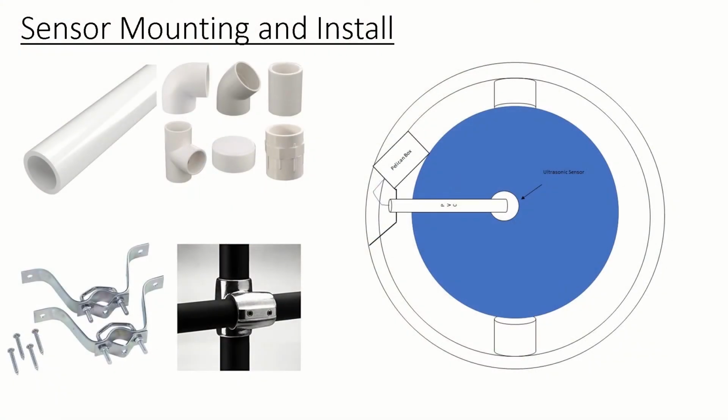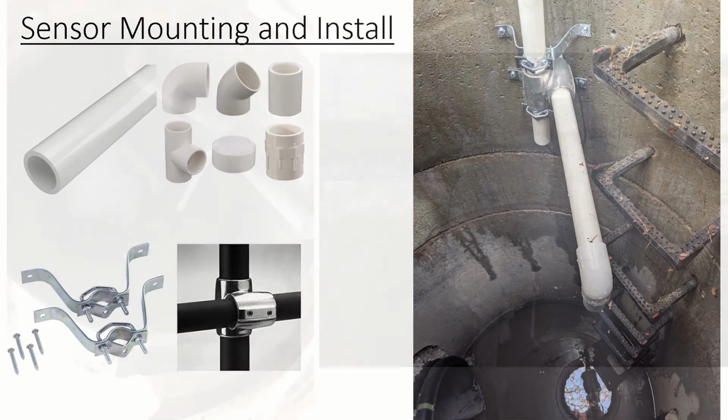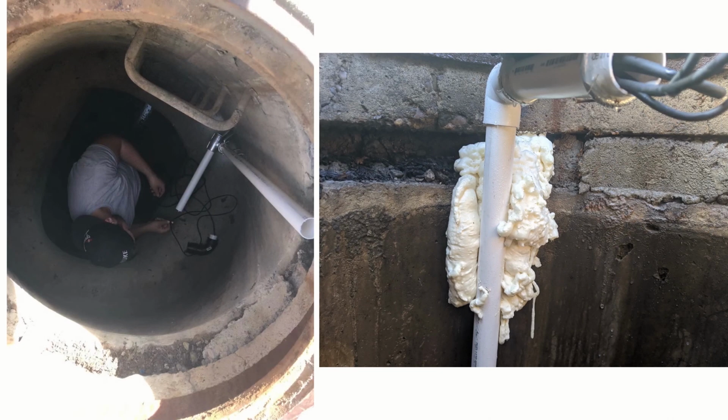Sensor installation is configured using a modular PVC chassis design for both the case and sensors. With the help of university facility plumbers, ladder brackets were hammer drilled into the manhole walls, and the PVC chassis was mounted using new rail fittings. Slight modifications were necessary at each site. For example, at the stadium site, the unsupported upper chassis near the case was secured to the wall using foam.